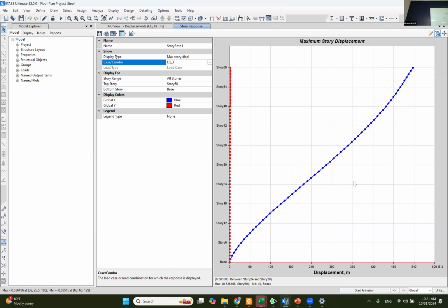0.6 meter. Okay, that's maybe not much, but from the serviceability point of view, we may need to increase the stiffness. By the way, in this one the columns were 1 meter, not 1.5 meter, and the spacing was I guess 3 meters. So with your lower spacing, and beams maybe smaller than yours, and shear walls of 1 meter, you're supposed to have something less than this number. But I didn't crack my sections. These sections are not cracked, so you have to crack your sections.